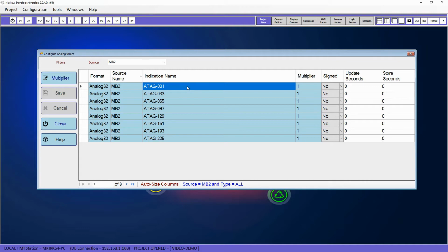If your control system uses a lot of fluctuating analog values, the constant changes can slow down your control system. Part of this slowdown occurs via the communications, the updating of your screens, and the recording of historical values for reporting and playback to screen. So to lessen the impact, the Nucleus developer allows you to filter and scale your analog values.